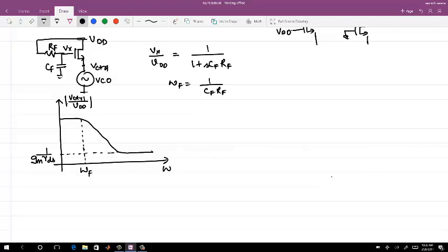In case you control VDD directly, let me just put it that way. VDD can be controlled as per V control. So let's say I do not want to change this part, then where should the loop filter output connect to? To VDD, right? Because the control voltage which is being passed to the oscillator is directly related to VDD here. This is just to do a simpler one.